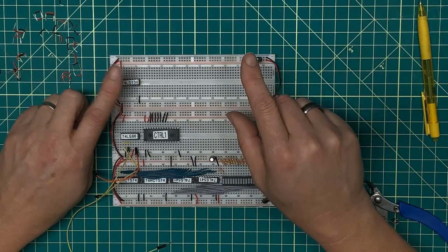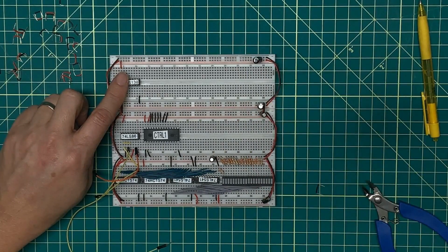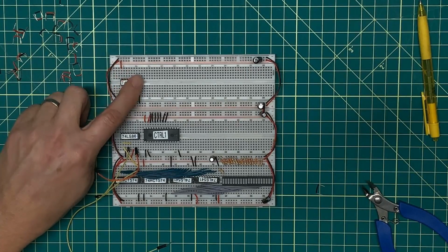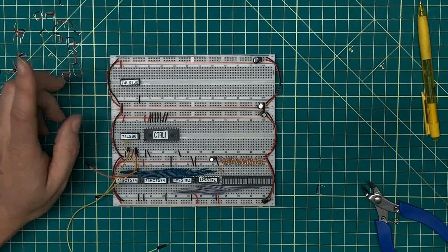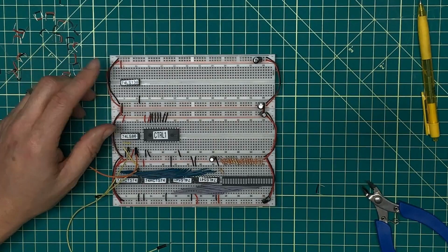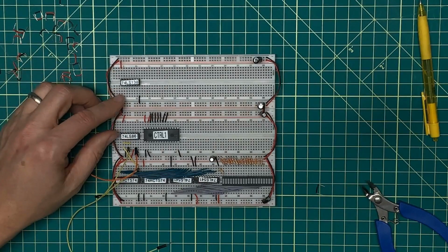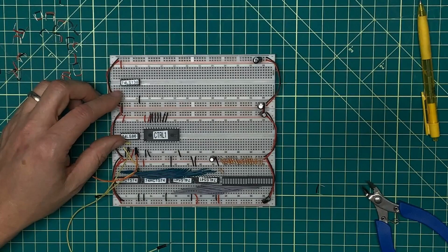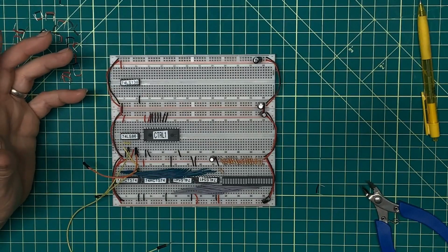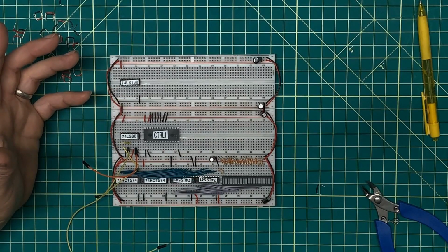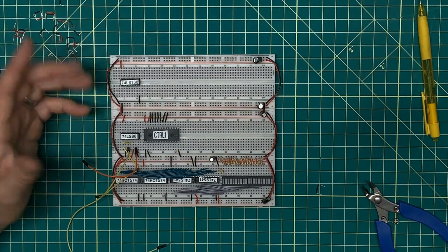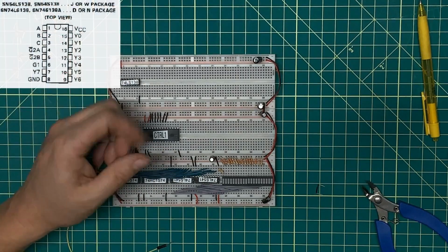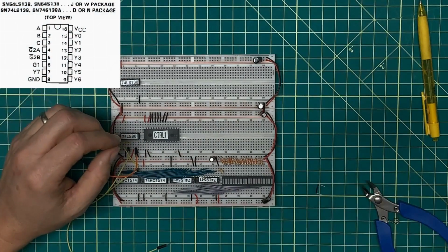It's not going to be triggered by the clock, which means that it's going to be a 45 nanosecond propagation delay from when the signals hit the inputs to when the output goes low. And because it outputs an active low signal, it's perfect for driving the line drivers, which require an active low signal. So I need to open this up for myself so I can see the pin diagram, and of course I'll put one up in the corner for you.